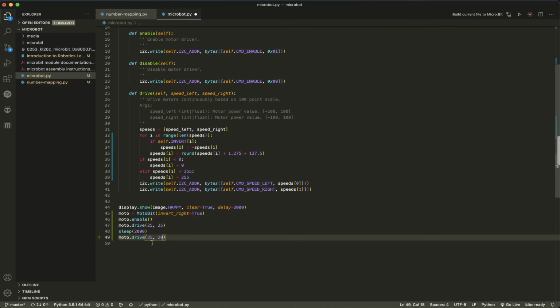And so now you can see that our left motor will go faster than our right motor. And so you can see now after 2 seconds of going straight, the robot would turn, not really turn right, but it'll curve to the right. And so you can play around with these numbers and increase the difference between them to make sharper turns, or curvier turns, right? Because if you make the difference really small, right, 35 and 30, you'll see the robot will drift to the right little by little. But yeah, feel free to experiment with this.